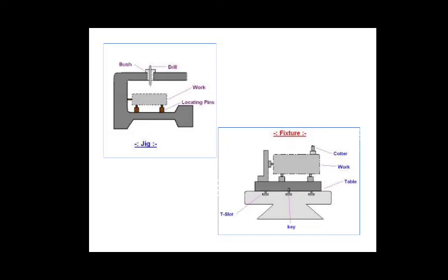Next, type and capacity of the machine, its extent of automation, provision of locating devices in the machine, available clamping arrangements in the machine, available indexing devices and their accuracy, evaluation of variability in the performance results of the machine, rigidity of the machine tool under consideration, study of ejecting devices, safety devices, etc. And the last point is the required level of accuracy in the work and quality to be produced.